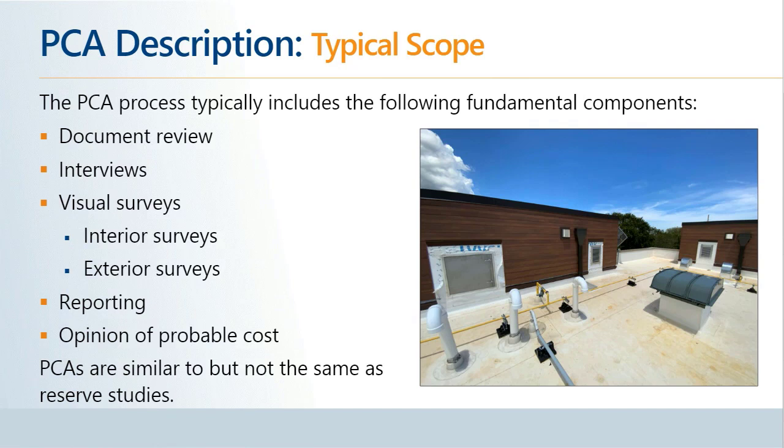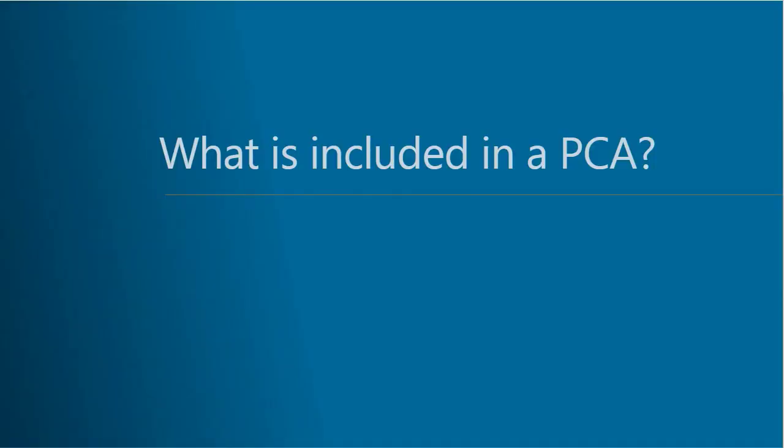One quick but important note, PCAs do share many similarities with reserve studies. That may be a term that you've come across. Reserve studies are often completed by property owners, specifically condominium associations, to develop long-term capital budgeting aimed at establishing an adequate cash reserve to fund future repair and maintenance needs. Reserve studies typically include both a physical analysis and a financial analysis. The physical analysis portion of the reserve study is similar to a PCA. I'll turn it over to George, who will discuss the primary elements of a PCA.